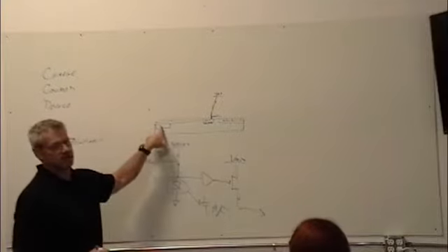Those numbers come out to amps. Those come out to like 1.5, 2, 3 amps on each one. So now you not only have a power supply that can drive that, but if you RMS it out, it's like 1/4 of an amp with 1.5 and 2 amp spikes on it. You've got a huge noise source as well. It's a huge noise source. It's going to get into everything.